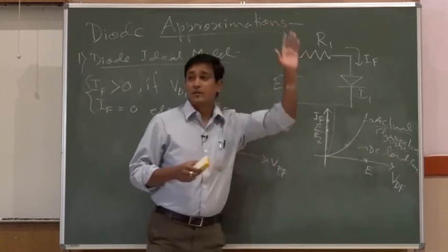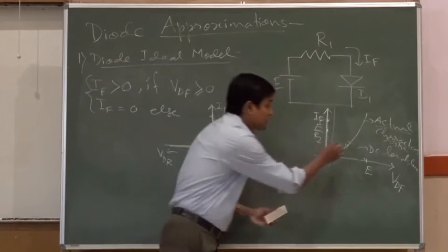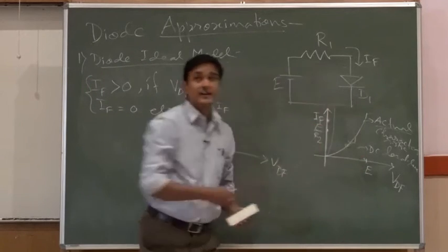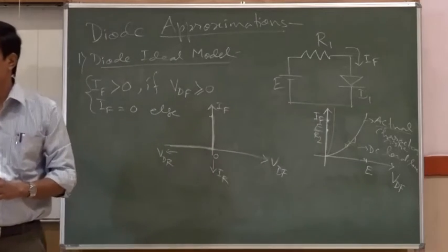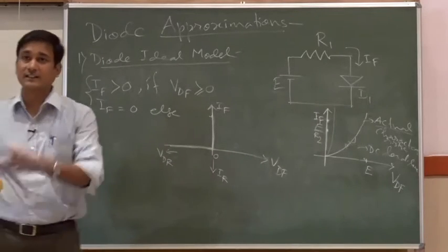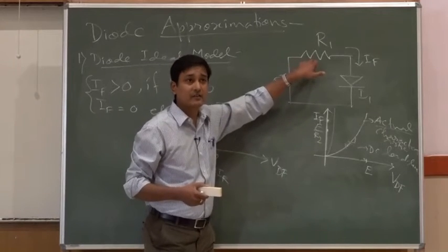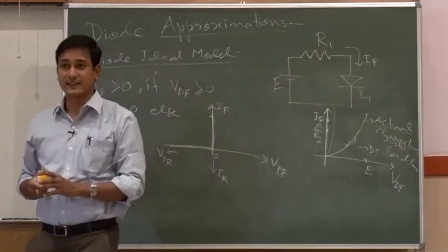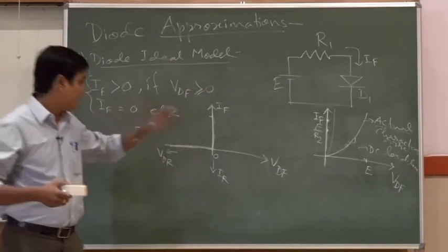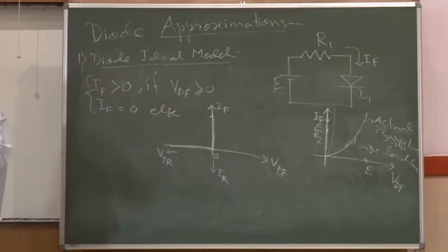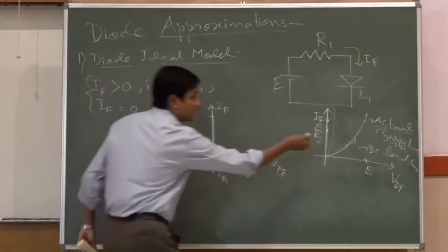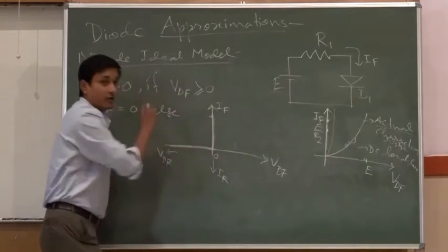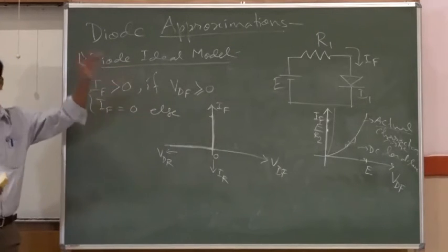Fine. So, it is purely an approximation of this curvature, where we are considering that with a small increment of this voltage, current will go very high, and with a small variation of this voltage, the current changes very much. So, the diode has nothing to do other than this electrical circuit element which is connected to that circuitry. That is why we say that in this condition, if the diode voltage goes beyond 0, things will be purely controlled by the external electrical circuit element other than the diode. Okay. So, that way we consider this actual characteristic in this form, where our model goes this way.